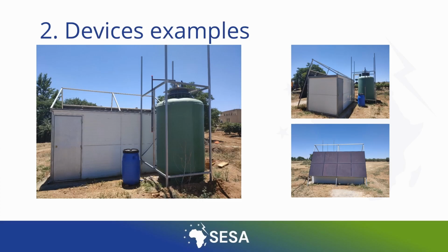An autonomous biogas system device is shown on this slide. It's prepared to work with solar energy. This energy feeds the agitation and sludge transfer pump to the digester and the digestate outlet. The digester consists of a deposit, the green one, whose temperature rises naturally due to the action of the sun. This device is designed for warm areas of the planet, where the digester doesn't need an extra heat input.